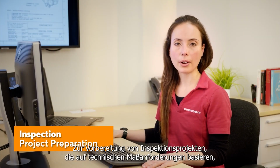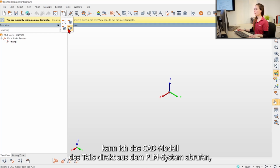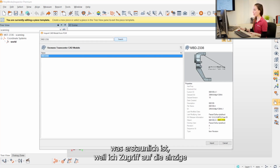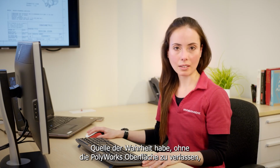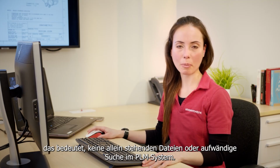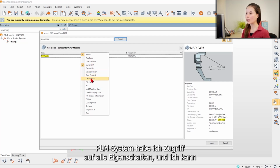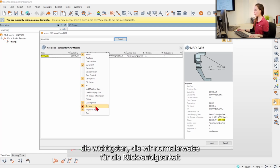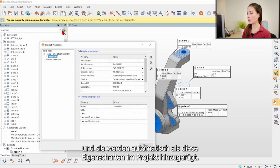To prepare inspection projects based on engineering dimensional requirements, I can retrieve the CAD model of the part directly from the PLM system, which is amazing because I have access to the single source of truth without leaving the PolyWorks interface. So no standalone files or PLM browsing for me. And not only that, but having a direct connection to the PLM gives me access to all the properties, and I can enable the key ones we typically use for traceability. And they will be added automatically as piece properties in the project.